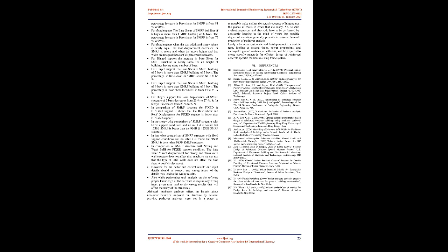Although pushover analysis offers insight into the nonlinear behavior imposed on a structure by seismic activity, pushover analyses are not in a position to reasonably predict either the actual sequence of hinging or the places of hinging in many cases. So, seismic evaluation and design have to be performed by constantly keeping in mind that a certain degree of variation generally prevails in the seismic demand prediction of pushover analysis.